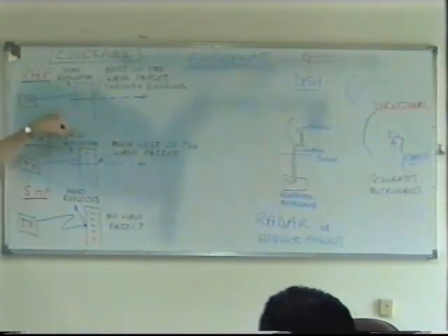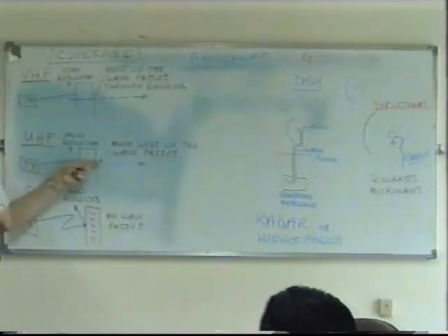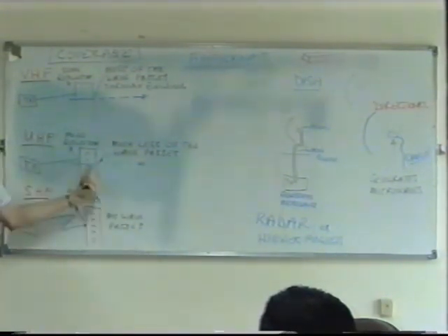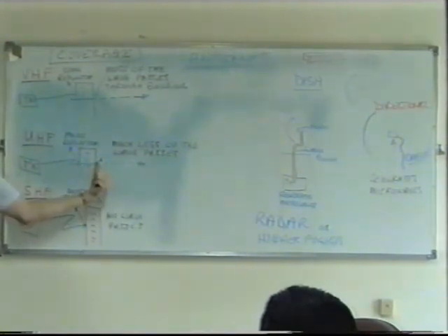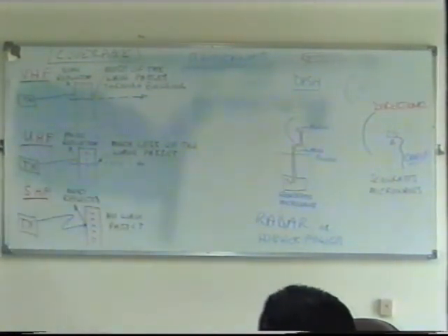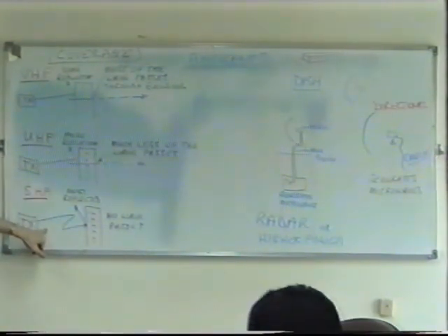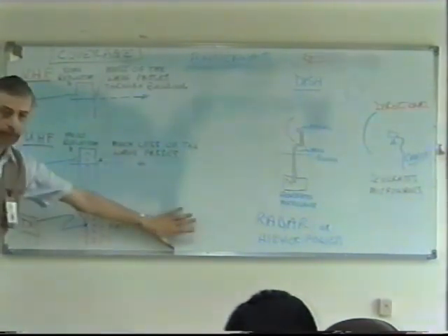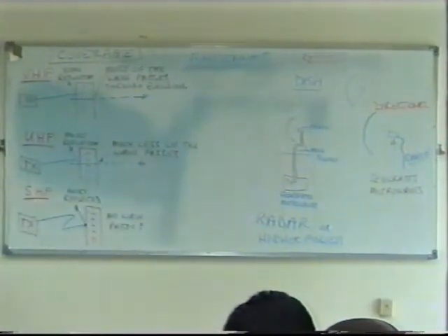We only get a little bit of reflection from buildings. UHF, we get more reflection and more attenuation as it goes through the buildings, meaning a lot of the energy in the wave would be lost as heat in the building, inducing electric currents into the structure of the building. And then finally, SHF, forget it. You're not going to get anything through the building there.